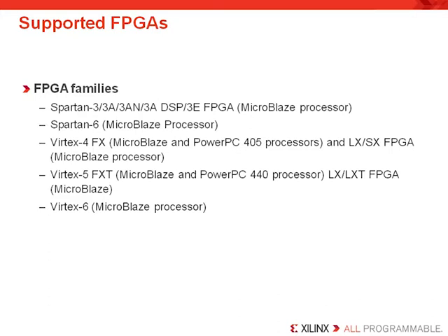All of these processor solutions are supported with EDK and include optimized peripherals that save customers from having to build the same IP over and over, and build it from scratch for that matter. Note that Xilinx's newest family members, the Spartan 6 and the Virtex 6 device families, already support MicroBlaze and do not have a dedicated PowerPC processor core.